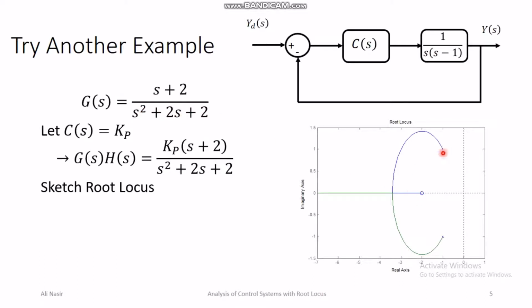And so this is already asymptotically stable, but adding a proportional controller does not destabilize the system, and also gives us a chance to have zero overshoot or reduce the overshoot, because the original system would have at least 5% overshoot. So if we want to get a 0% overshoot or 2% overshoot, then we can have it. And also if we want to keep the system going faster, then we can have it.